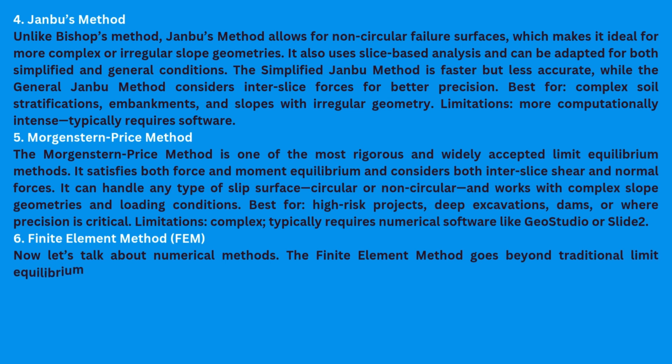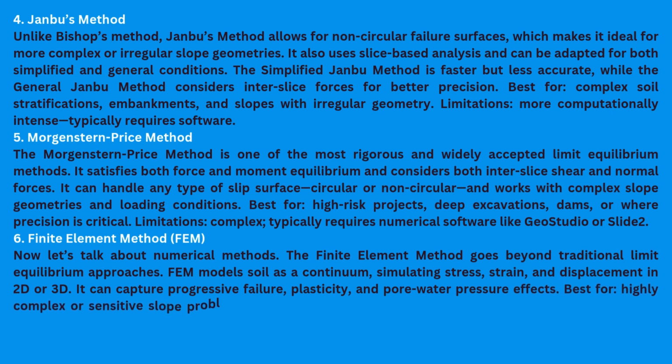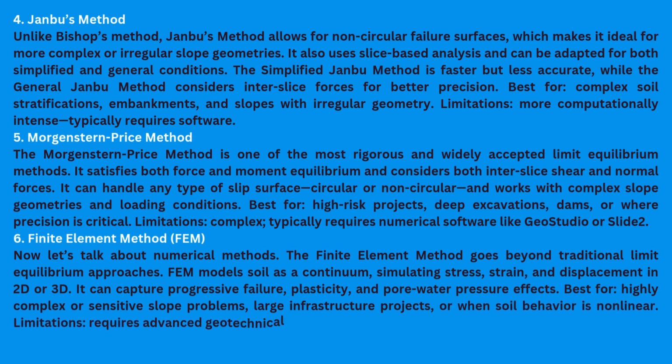6. Finite element method, FEM. Now, let's talk about numerical methods. The finite element method goes beyond traditional limit equilibrium approaches. FEM models soil as a continuum, simulating stress, strain, and displacement in 2D or 3D. It can capture progressive failure, plasticity, and pore water pressure effects. Best for highly complex or sensitive slope problems, large infrastructure projects, or when soil behavior is nonlinear. Limitations: requires advanced geotechnical knowledge and powerful software.